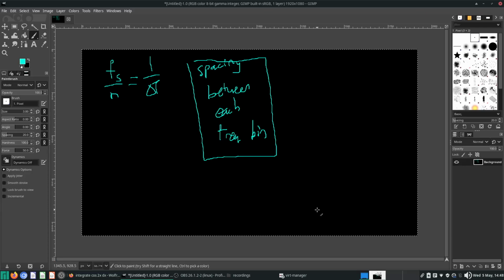All right, so we want an array starting from, let's say, 0 Hertz or 0 radians per second, whatever unit you want. You go all the way up to about whatever your sampling frequency is. If your sampling frequency is 2 Hertz, then around 2 Hertz will be your last number. Everything in between will be evenly spaced. Okay, even spacing.